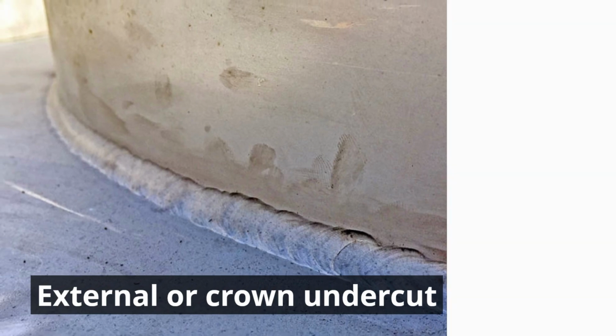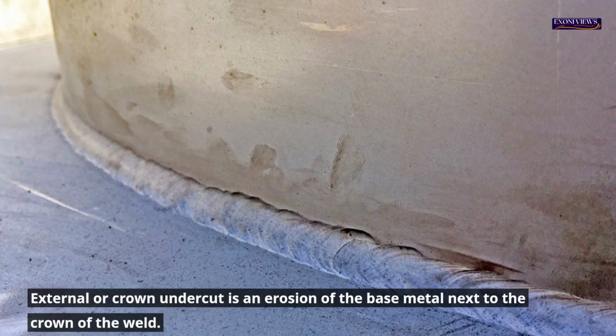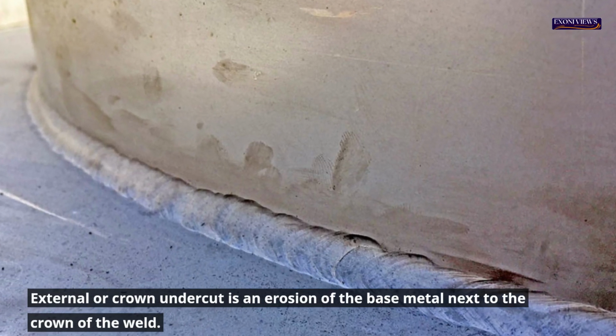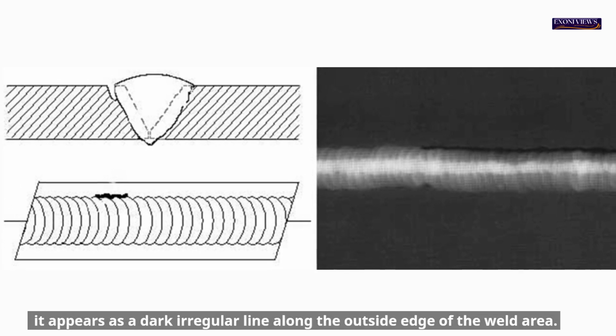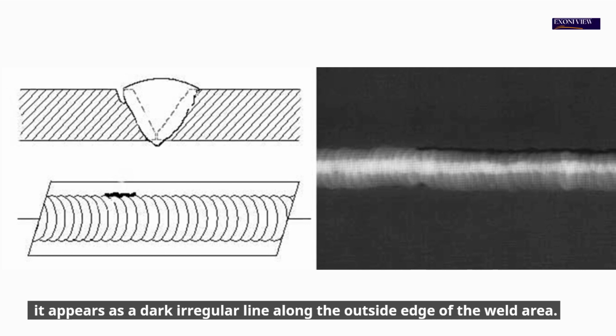External or crown undercut. External or crown undercut is an erosion of the base metal next to the crown of the weld. In the radiograph, it appears as a dark irregular line along the outside edge of the weld area.